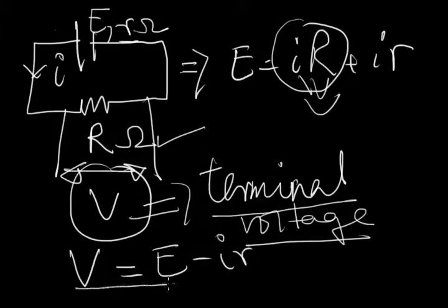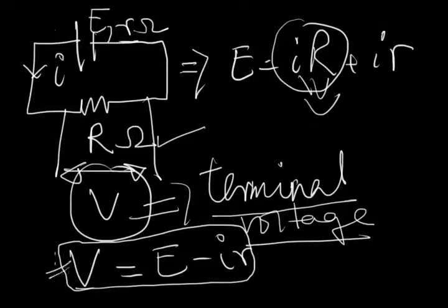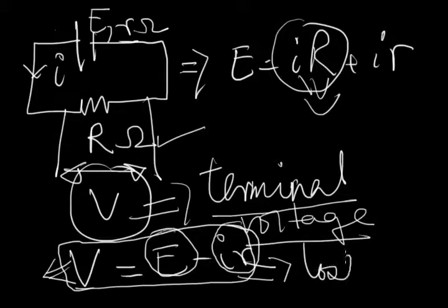That is the equation for Ohm's law in a closed circuit, where the external potential drop or terminal voltage is connected with the EMF. Since we do not have this much voltage across the external resistance, we call this a lost volt. So what we finally have is the equation V is equal to E minus Ir.